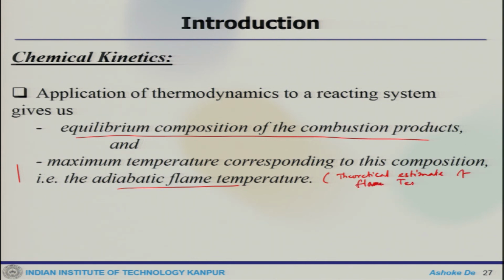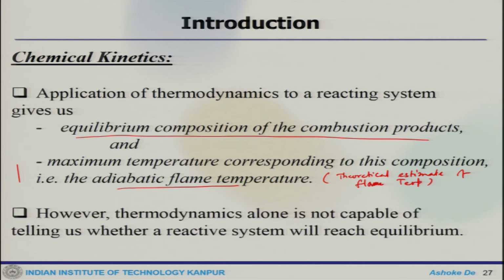of flame temperature for a given reacting system or for a particular fuel and oxidizer. If you change the fuel, this theoretical limit changes. So, thermodynamics talks about these things, but at the same time one has to note that thermodynamics alone is not capable of telling whether the system will reach equilibrium or not. So, that is another issue.